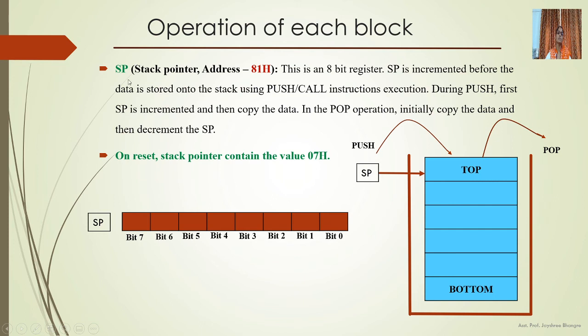Next important SFR is the stack pointer. This is used for stack memory. So stack refers to an internal RAM used to store and retrieve data quickly, and stack pointer is the register used to hold an internal address which points to the top of the stack.